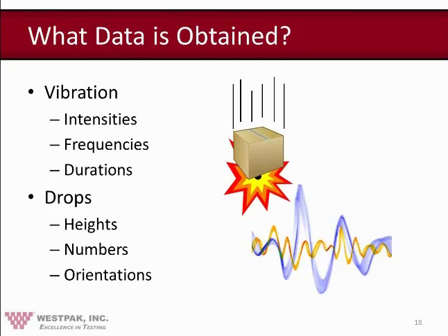We know that vibration input comes from transportation vehicles: trucks, aircraft, rail cars, ships. That is, the intensity and frequency of the vibration input vary randomly with time. So we know that they are random inputs. Thus, we are interested in defining the spectrum, acceleration versus frequency, that typically results from typical vehicles. We know that these numbers will vary depending on the load within the vehicle, the height above the floor in the vehicle where the product might be resting, and a bunch of other variables.